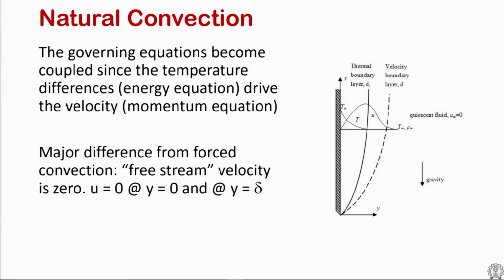So, the hot air starts to rise because of the emerging density difference. Depending on the Prandtl number of the fluid, if we stick to Prandtl numbers greater than or equal to 1, then you see a profile as shown in this figure, such that the thermal boundary layer is developing closer to the wall, and the velocity boundary layer is farther away, shown as the dashed line here.